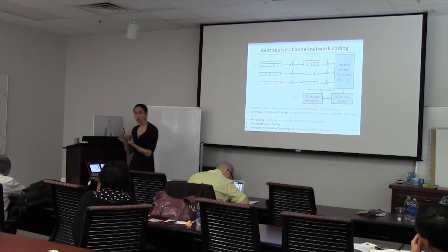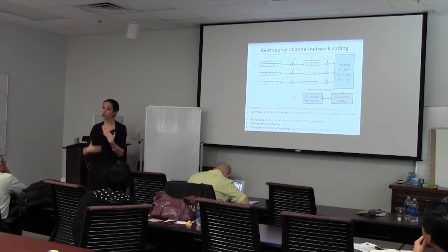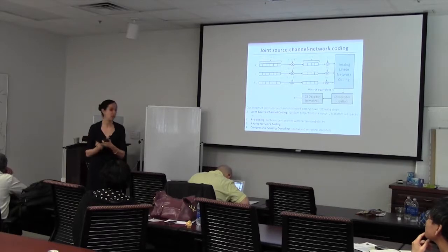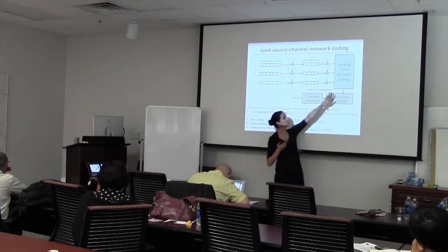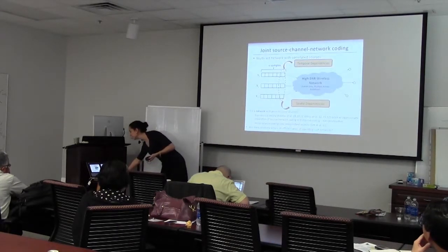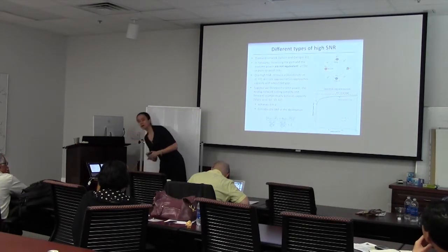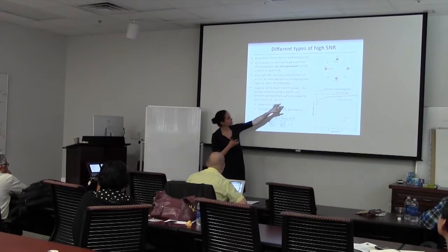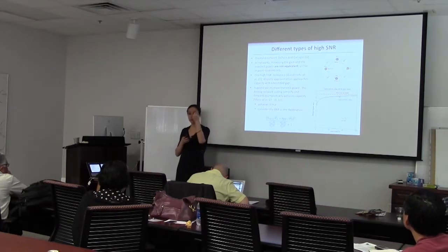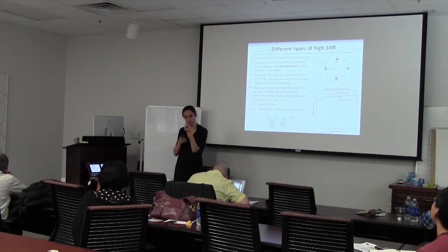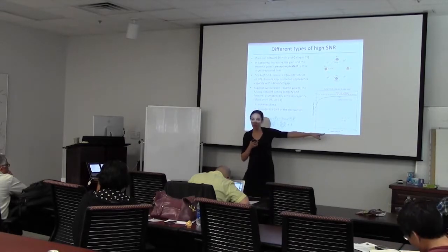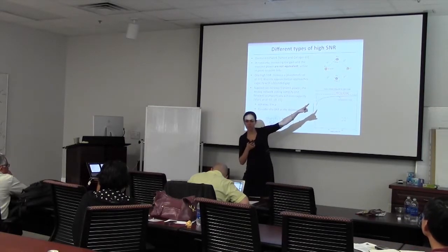Remember that I actually don't know if this is getting me close to the optimum. All I can do is give you some guarantees, but I don't actually know what the optimum is in this case. At least I know what the capacity of this is. And by the way, the analog network coding, this is maybe something I should have emphasized a little bit. I was just giving this little example here, but the analog network coding gets me not just to a bounded gap, but actually to a gap that goes to 0, and not just per degree of freedom. It actually gets to capacity, if the growth of the SNR is with the transmit power, not with the gain. Okay.